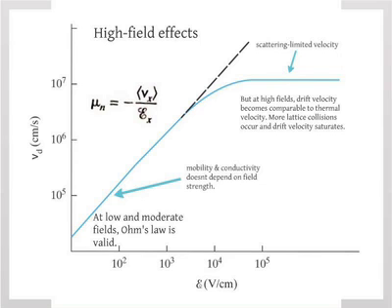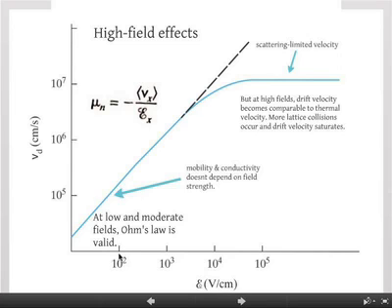Yes, but what is the field? That's correct. So it is the applied voltage over the distance over which the voltage is applied, right? So it's 10 volts divided by 0.1 centimeters, or 100 volts per centimeter. So let's look at it. It's 100 volts per centimeter here. So it's low field, and you can apply Ohm's law.